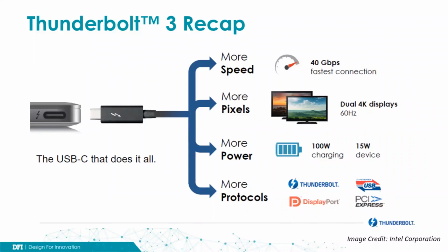Because Thunderbolt 3 has PCIe protocol, it can connect to PCIe devices like external GPUs or other PCIe cards via PCIe chassis. Also, Thunderbolt 3 supports daisy chaining. Up to 6 compatible devices can be connected in a Thunderbolt port instead of connecting to the host device. With USB-C, these devices would all need to connect to individual host USB-C ports.